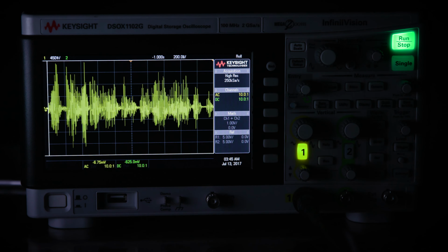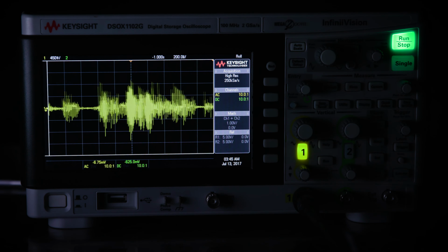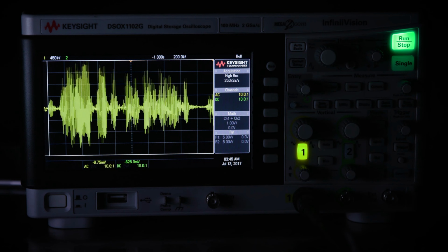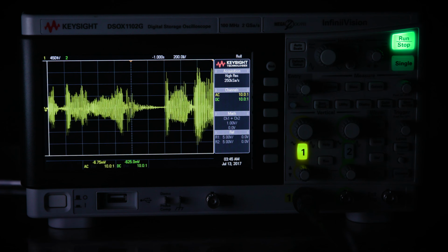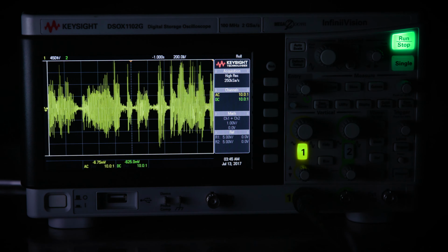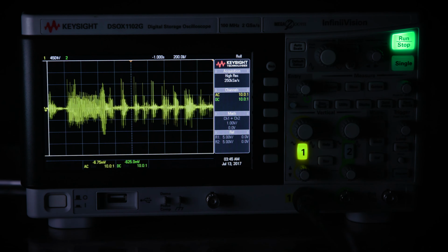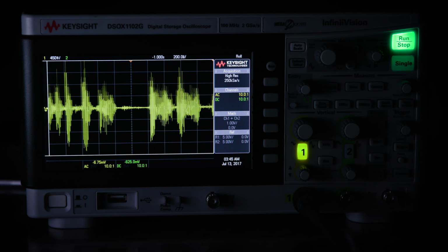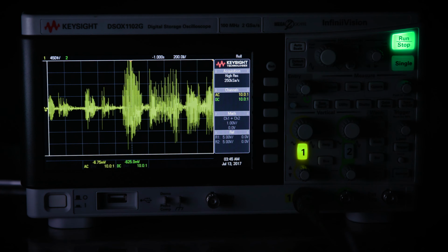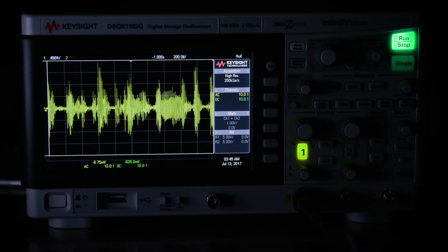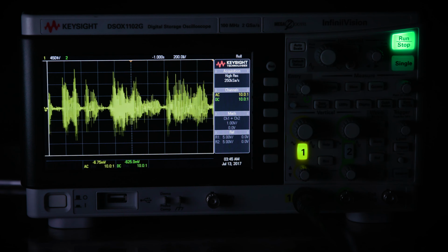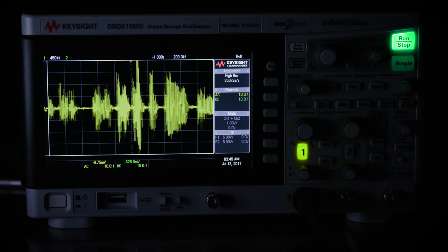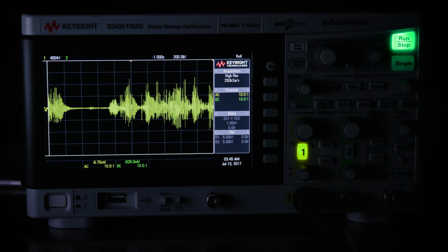We were going to have you look up a scope for us, see where our ADC was. Sorry, yeah, and you can interleave. You're right. 80 gigasamples for the 30 gigahertz channel, and interleaving two of those gets you to 63 gigahertz, supported by 160 gigasample sample rate. Now that's not one physical A to D sample, right? That's a system that accomplishes that. And that's the samplers out in front that distribute the samples, analog, to the A to D converters that then translate those. And that whole architecting of the sampling system is again one of the big challenges.